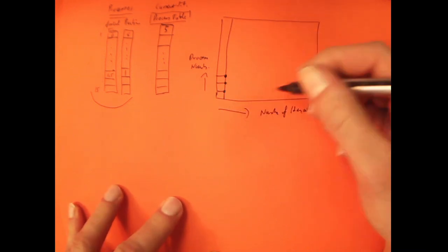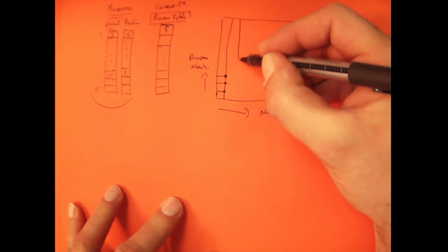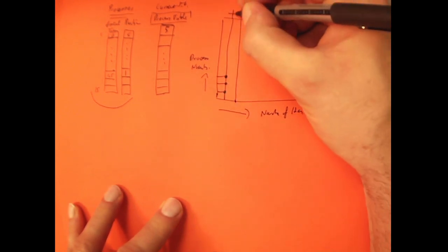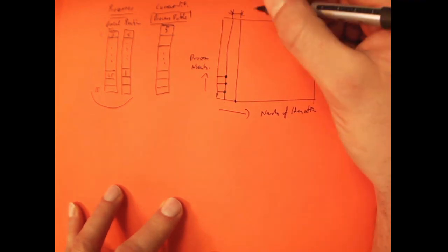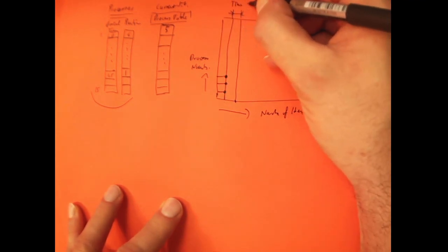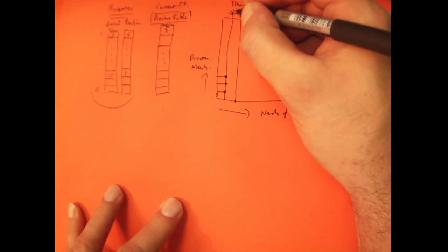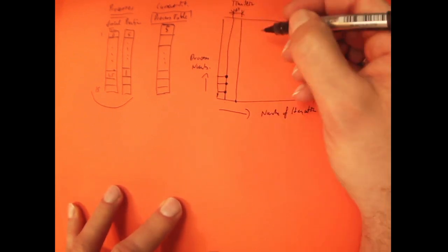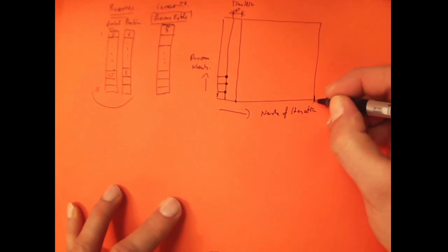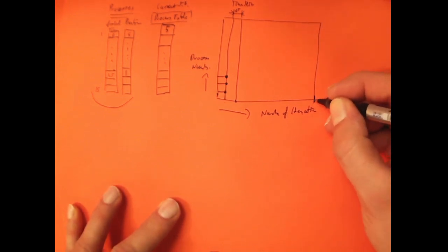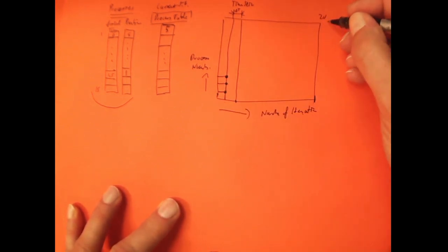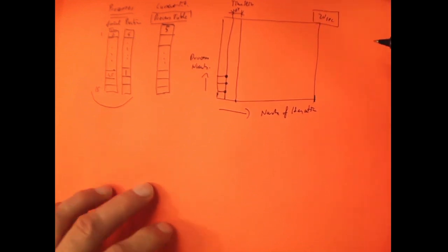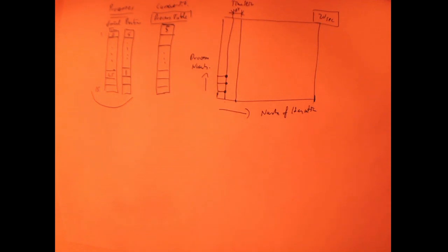So with this setup, I can define per iteration step, and from iteration to iteration we have exactly the time slice, or the delta t here. So delta t, at each operation we have exactly this time step, and after the number of iterations we have, in our case, the 20 seconds interval, so our complete simulation time.